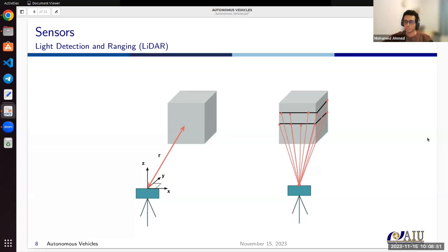So what is the LiDAR doing? We are talking now about a 32-channel LiDAR. It fires 32 laser beams, then it moves a little bit horizontally, and then it fires 32 and moves a little bit, and fires 32 laser beams and moves a little bit.